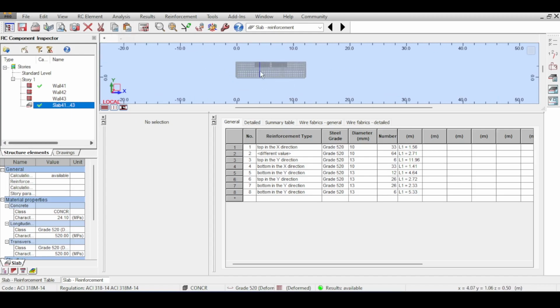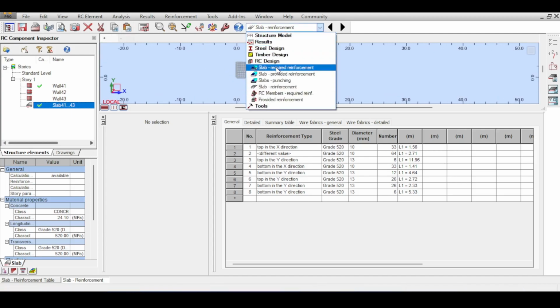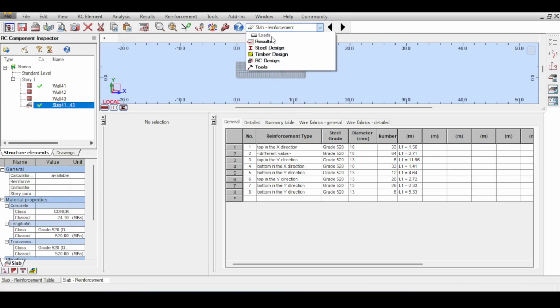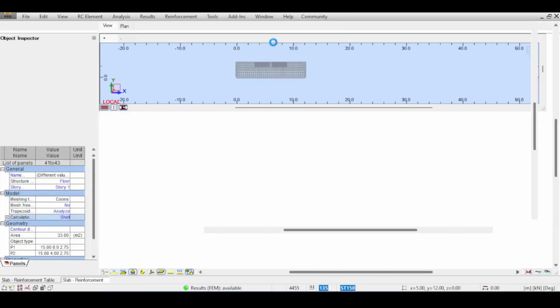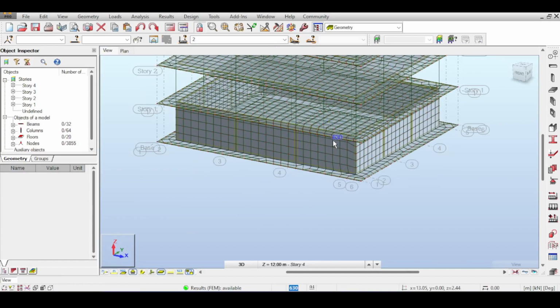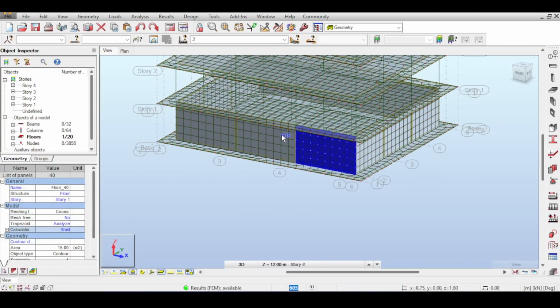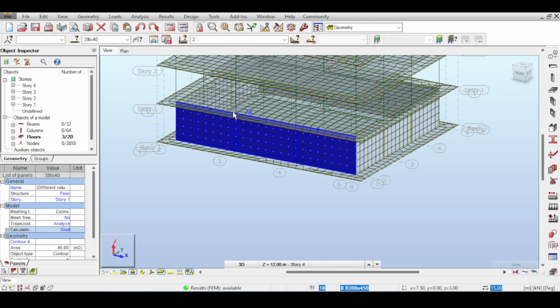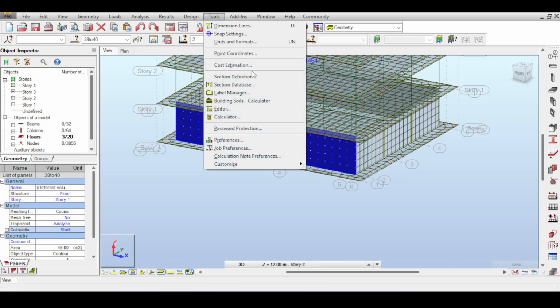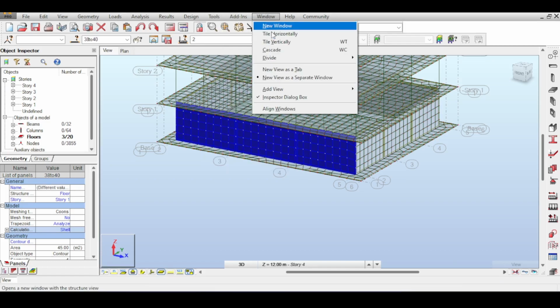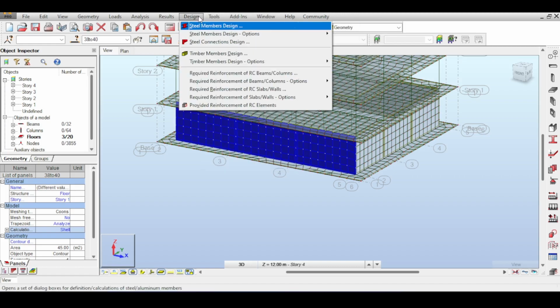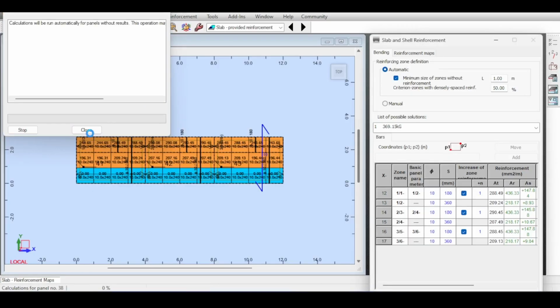Of course, that's one slab. I need to do all the basement walls. So let me go to the structure model now and go to geometry and select me another wall. So I just select those 3 walls now. The cool thing is, if you select 3 shells or slabs and then you ask it to design it, it understands you are talking about 1 unit and it takes them all as 1 unit and even provides you with a continuous steel bar. Allow me to explain.